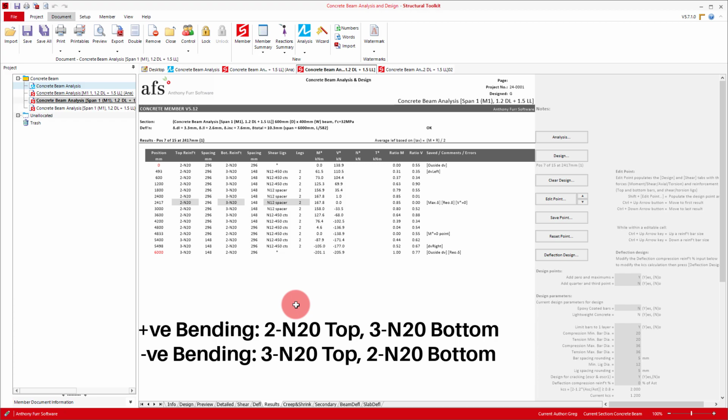For our shear reinforcement, there is a short 1200mm long section where ligs are not required, designated by the N12 spacer. However, for simplicity, we would likely adopt N12 at 450 centres along the entire span. There will also need to be consideration of lap lengths and other detailing requirements, such as where the bar numbers change, but this is beyond the scope of this video.